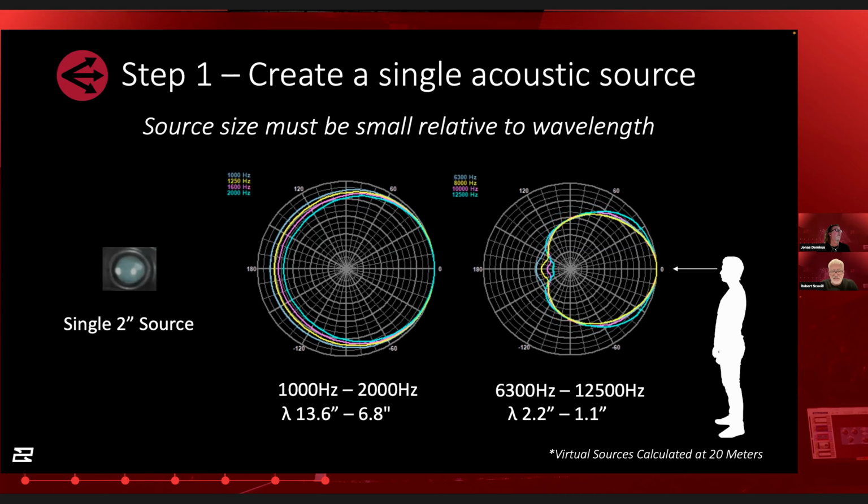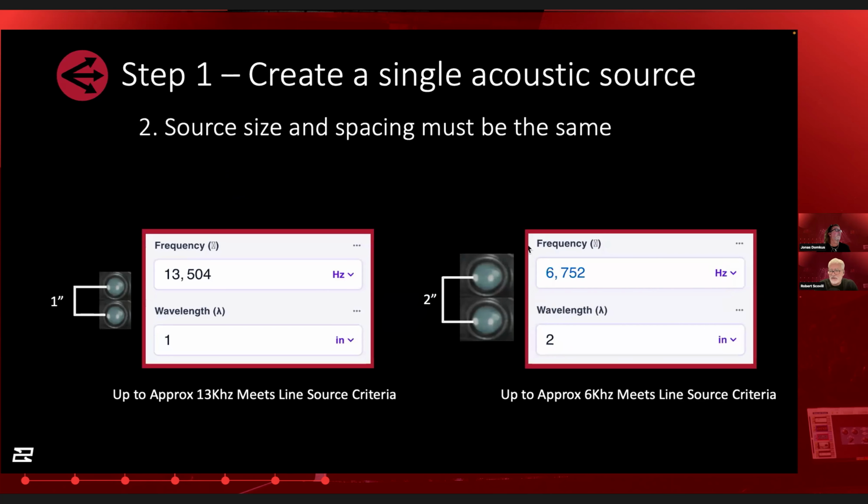But as we start to stack these drivers vertically, we're going to create collapse, but we're also going to create other issues. And that's because of the timing offset, right? As we move off axis, there's going to be different arrival time from the top one to the bottom one, and it's going to create some issues for us.